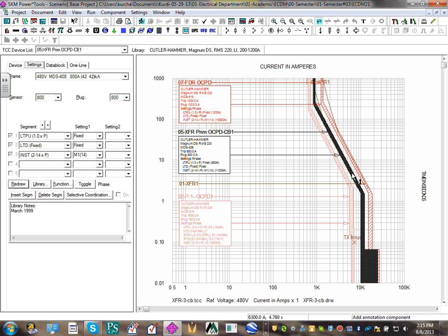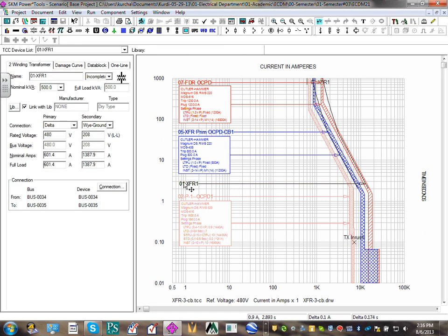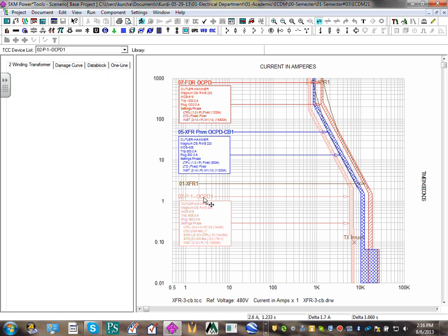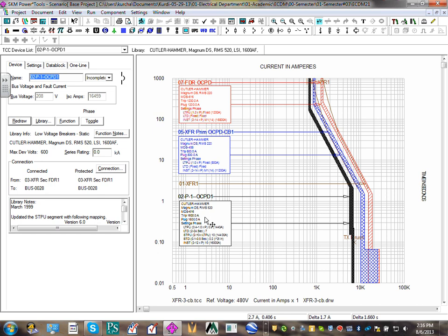And I adjusted it. So I'm allowing my circuit breaker to, can you see this leg here, moving this leg here? If I move it this way, my transformer, every time I start, it's going to trip. So you try to move the instantaneous far enough that it clears the inrush. Here's my damage curve for my transformer, it's protected. And here's my secondary side, which is happy to be a 1600 amp.